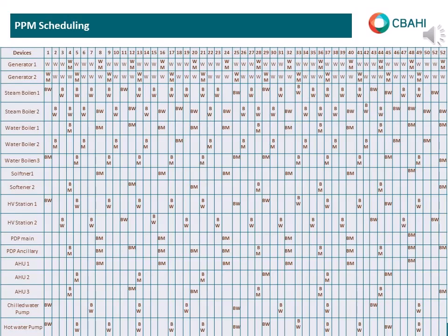Plus a very important note: you do the PPM for winter machines, for example the heating, in summer, and for summer machines like the air conditioning, you do the proper PPM in the winter. That way you can avoid discomfort or problems for your staff and patients. You don't do maintenance on the air conditioning in the summer, or everybody will feel uncomfortable.